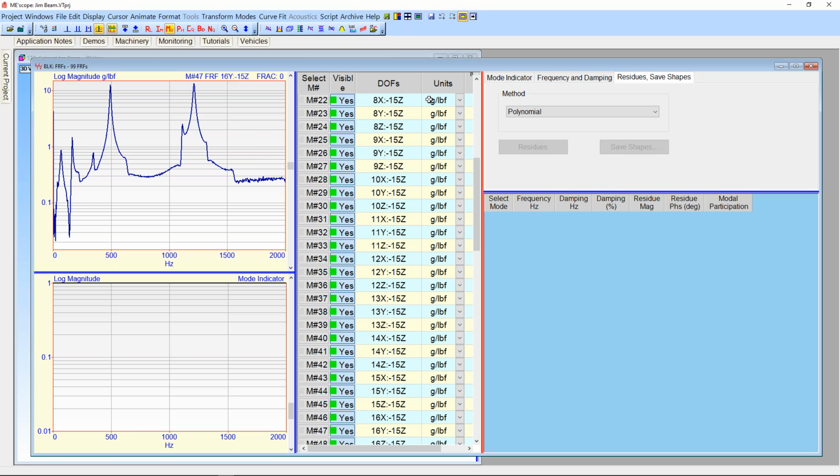So regardless of what the spectrum of the force looks like, and when I hit a structure like the gym beam with a hammer, it's going to excite a lot of frequencies. I want to do that. And it's going to have a certain spectrum of the force input, which is measured with the hammer, with a load cell attached to it on the head. But when I get to this stage, I've divided the spectrum of the acceleration by the spectrum of the force.